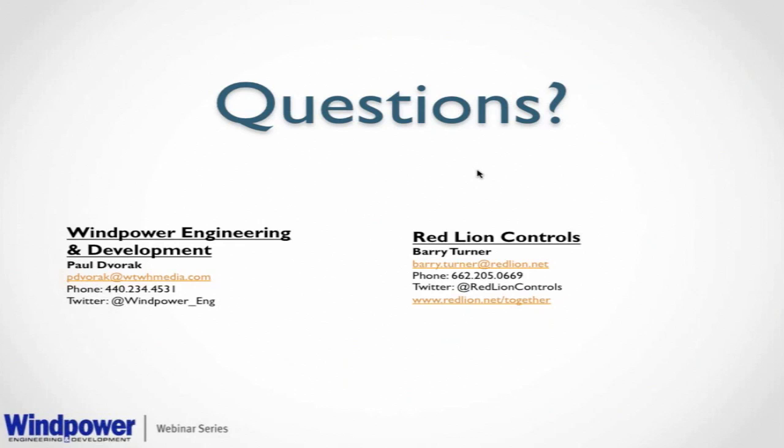Okay, very good. George asks another question that is on my mind too, is what type of fiber connector do you see the industry standardizing on? If you're looking at 100 meg, it's going to be ST. That's what I see for the most part, ST type connector. And ST is probably my favorite because, like I said, it's got that stab and twist, or it's got a BNC type connector. You can push it in and twist it, and it's locked in place.